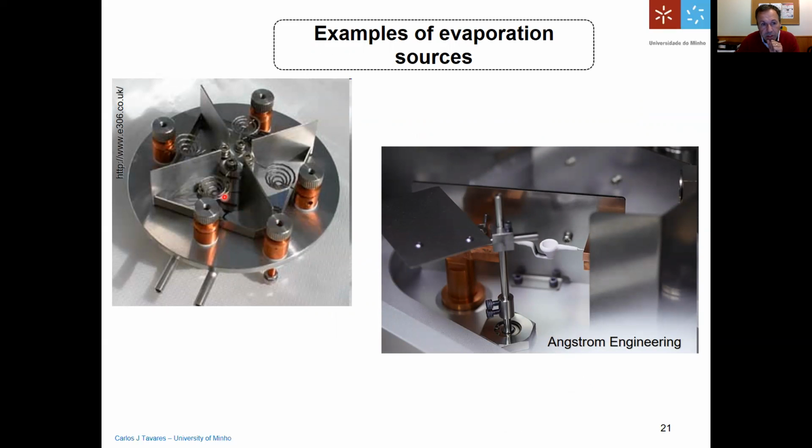For example, instead of only one evaporation source, you can have 4. So for example, you can be evaporating 4 different metals at the same time, or 4 different compounds, or just using 2, or initially using 1, then using the second one, then the third and the fourth. You really need to have separate crucibles or separate baskets, because if you're using these kind of baskets, they usually become very contaminated due to the evaporant, and you cannot reuse them with different material.